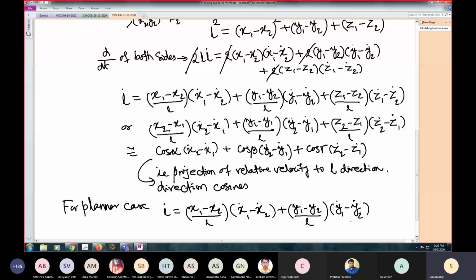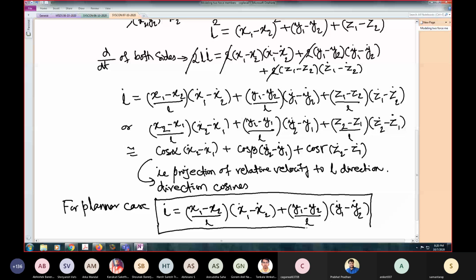So if this is the kinematic relation, the forces must as well transform accordingly, because we know all our constraints, 1, 0, transformer, gyrator, all those things are power conserving. There is no loss of power there. So if you represent kinematics correctly, forces will also accordingly represent correctly.